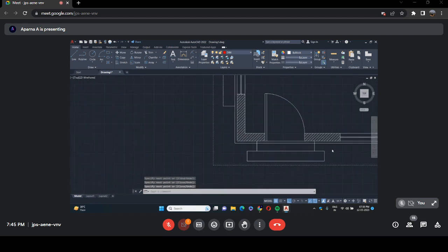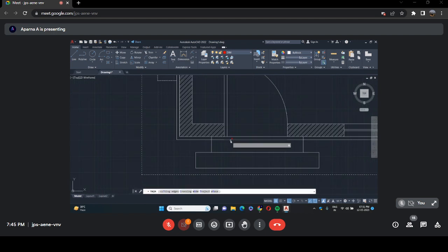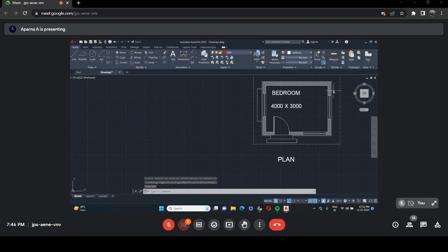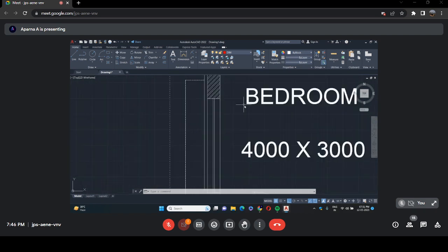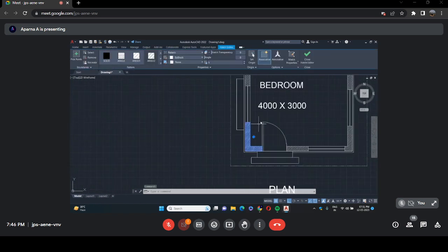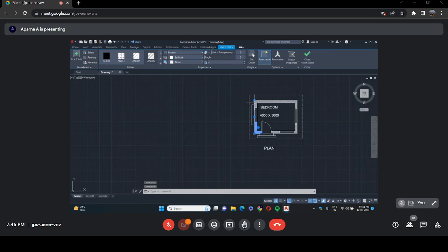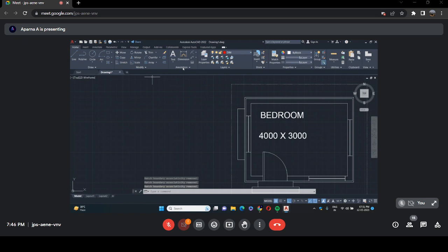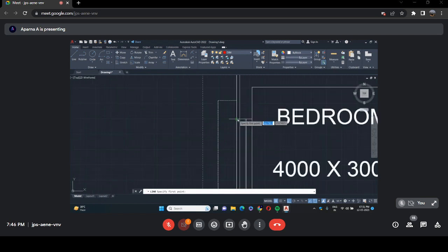Okay, now I can trim off the plinth layer over the step. Now the step is complete. Okay, I forgot one thing. You need to draw lintel over the window also. In order to draw lintel over here, I need to remove all the hatch. Lintel is very important. So the length of the lintel is 10 centimeter. Here it's 100 units. Drawing line, 100, enter.